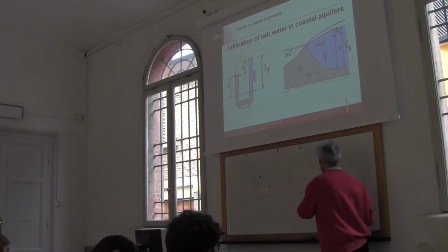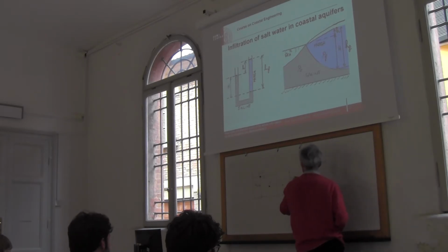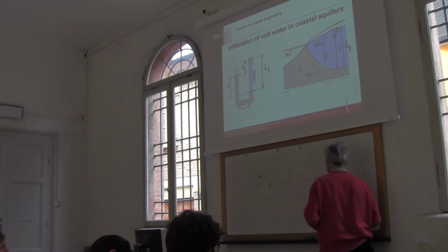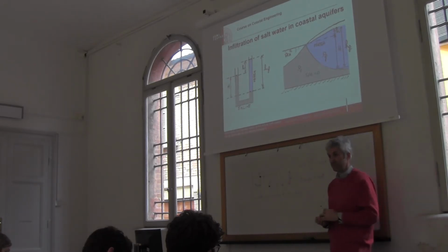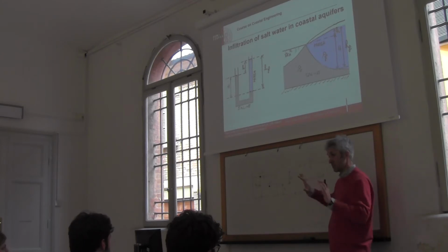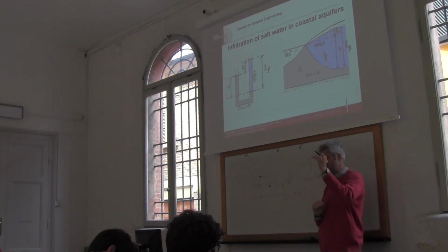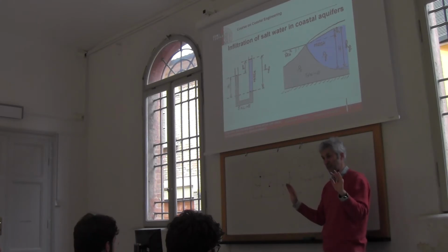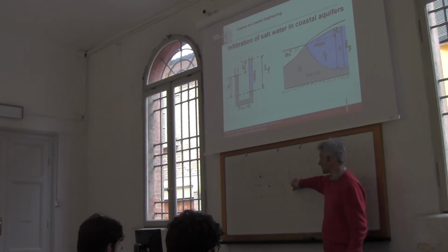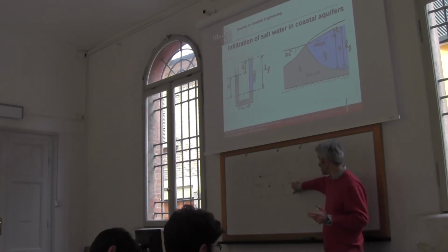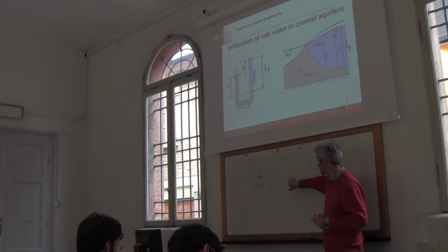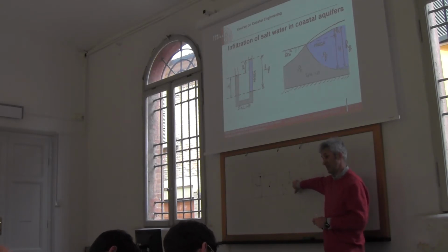So basically, if I apply the hydrostatic law, I could say that my constant is Z max, because the pressure is 0. So it works. In this way it perfectly works. Increasing Z means decreasing pressure. Okay, that's fine. My only problem was that I made reference to H, and this is fine, but if I want to make reference to H, I have to change the sign. And I have to change the sign because increasing Z means decreasing H.